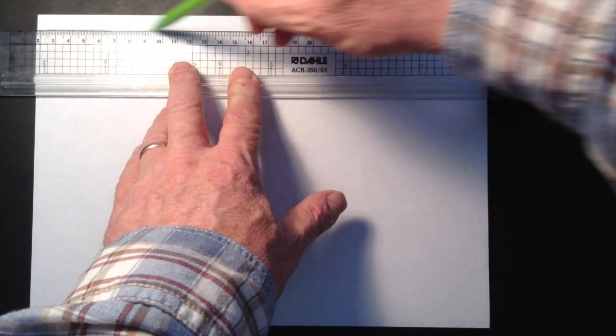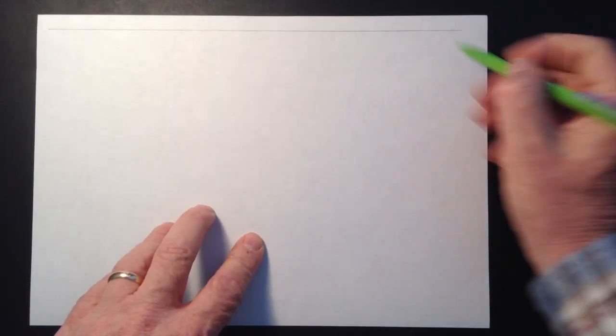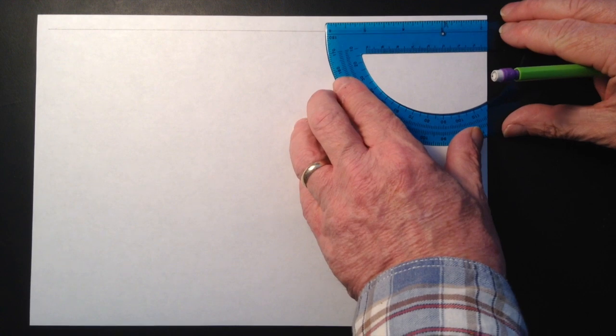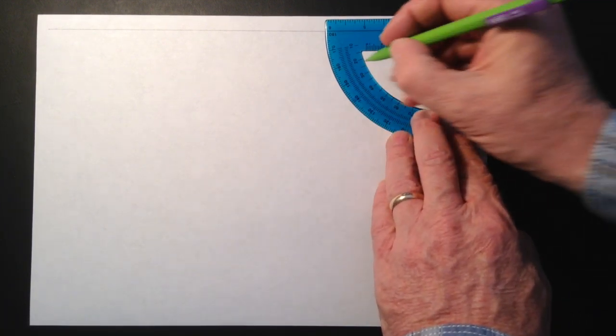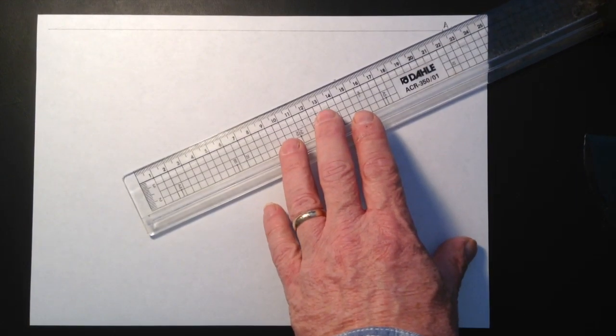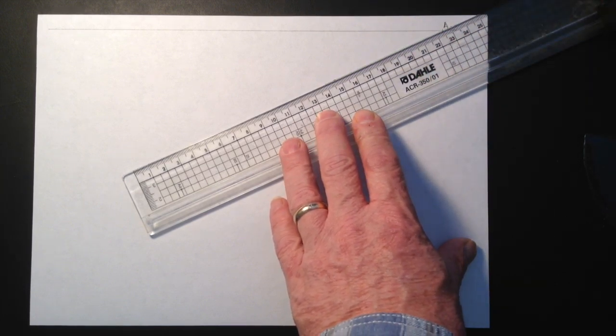Okay, let's make a start on our velocity diagram. Let's start with a baseline. I've flipped my paper. It doesn't really matter. I just wanted to give myself a better scale. So there's my baseline and my first point A, which is on the crankshaft. Now, we need our angle, 25 degrees if you remember, so no substitute for using decent instruments and a decent scale. So let's get a construction line in 25 degrees away from our baseline, like that.